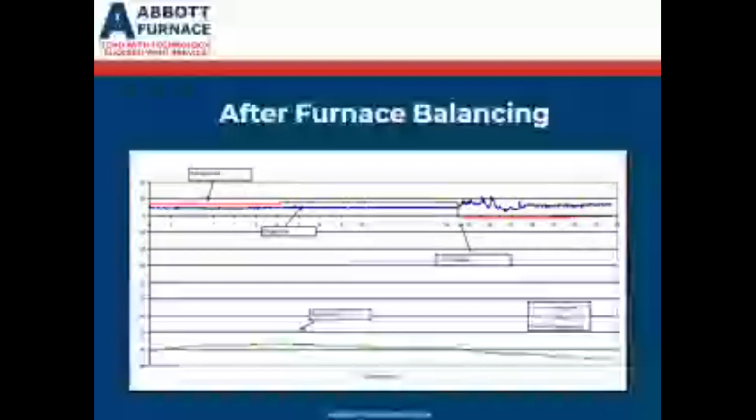And once we get back into the heated zones, that dew point will lower to where we can get the bonding and the sintering. And then the dew point in the back of the furnace is very low because we're just using nitrogen back there as a buffer between air coming up the back of the furnace as the parts go through the cooling chambers.